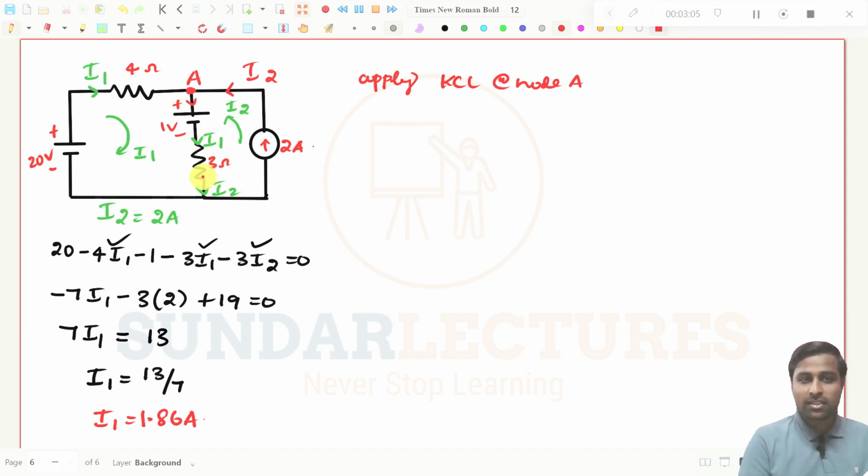So I am taking it as I through 3 ohms. I1 is coming in, I2 is coming in, I3 is going away. So I1 plus I2 will be equal to the current through the 3 ohms resistor.